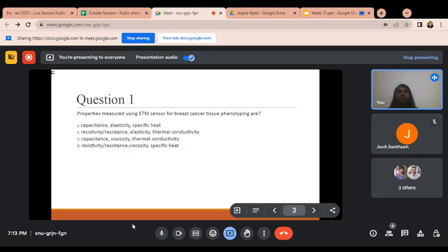DI water is 5 and the others are 1. We prepare this solution in this ratio, dip the wafer into it, and after some time dip the wafer into the DI water, then using the nitrogen flow we can dry the wafer.